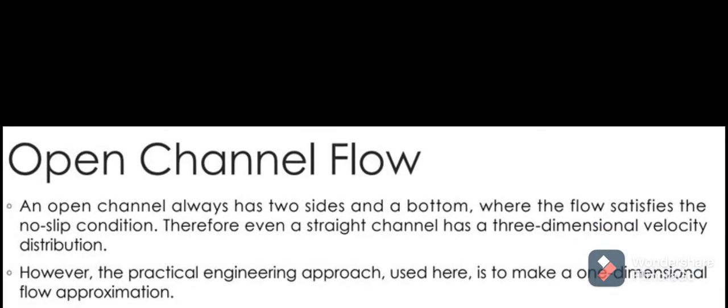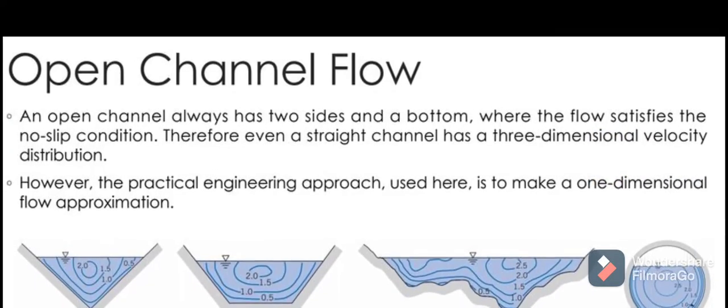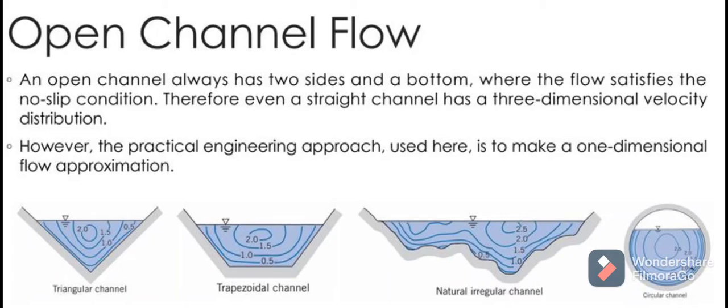An open channel flow always has two sides and a bottom. When the flow satisfies the no-slip condition, there are different types of open channel flow such as triangular channel, trapezoidal channel, natural irregular channel, circular channel, etc. The practical engineering approach is to make a one-dimensional flow approximation for an open channel flow.